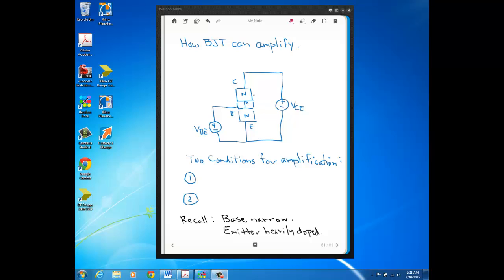So you wouldn't want to actually take a BJT and connect sources directly up to the base emitter and collector emitter like I have here, because you would burn up the transistor. But this discussion is just for conceptual reasons, and I wanted to keep the circuit as basic as possible. In a future video we'll actually look at a practical BJT amplifier circuit that does have resistors in these paths.